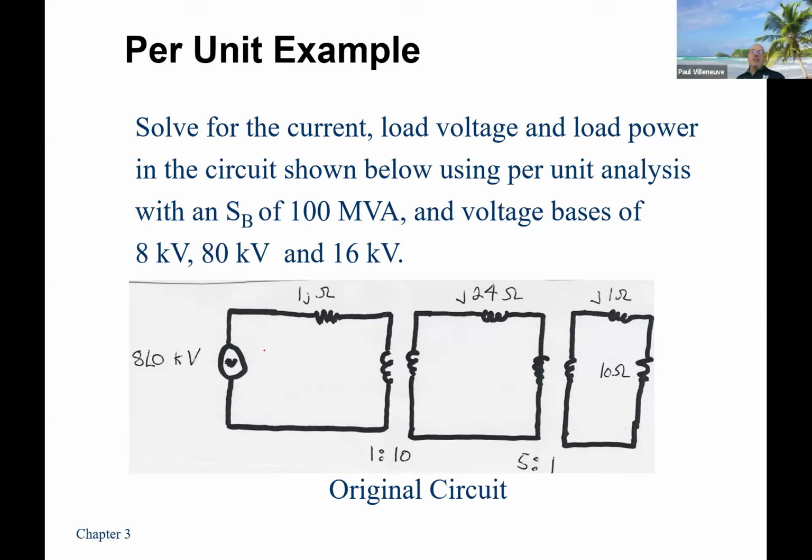Then we're going to step that down to deliver to our load. And then our internal transformer impedance there is about the same. It's j1 ohm. And finally, our load is about 10 ohms of resistive load. Remember that ohms tells me that's real power. I'm getting paid on megawatt hours based on that 10 ohm load. Everything else, I'm not getting paid for.